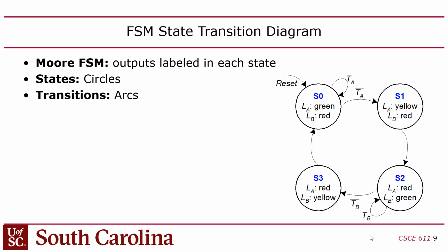So first of all, if you were designing a traffic light controller, you wouldn't do it with a state machine. I mean, not a hardware state machine. You might do it with a software state machine, right? You might implement this in software, but you'd have some kind of microcontroller running in there, because it's a lot easier to design software than it is hardware. So why would I try to do everything in hardware, right? Especially since it's not like I need it to be really fast. The clock is running at like a 5-second period here. So you would never design something like this in pure hardware.